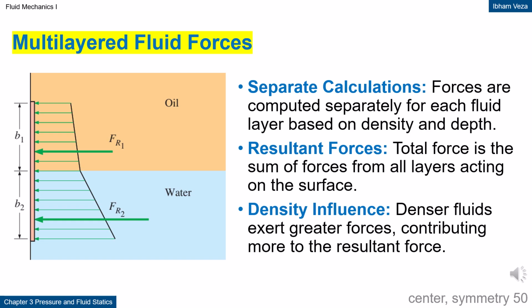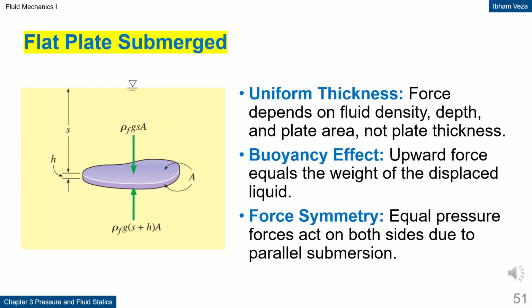Denser fluids have a larger influence. This approach is important in stratified fluid systems. Flat plate submerged. The force on a thin submerged plate does not depend on the plate thickness, but on the fluid density, depth, and plate area.